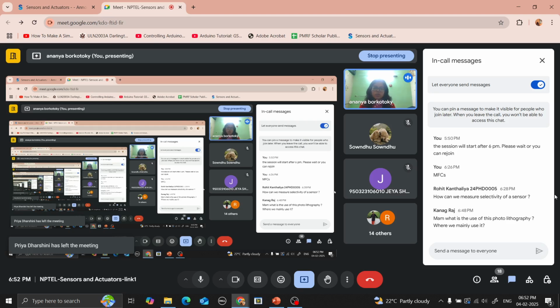Now say due to different concentrations of acetone, the resistance of the material will change. Now how will you measure the change in resistance? You will first make some electrodes. There are many examples that were given in the lecture videos also. You have seen how electrodes are made, and that there are different configurations of electrodes. It can be simple two metal lines, or it can be interdigitated electrodes like this. Okay, so how do you make it?